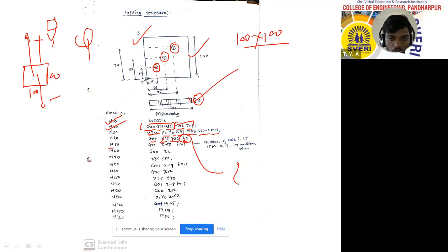In this block you can see N50 G01. That means linear interpolation, meaning the tool which is above will go down linearly.